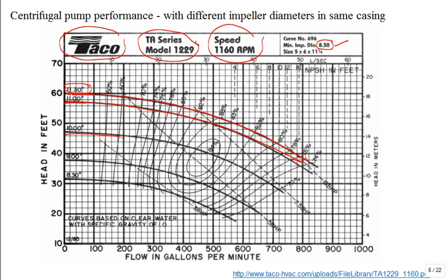This is the 10-inch diameter impeller. This is the 9-inch impeller. And the 8.3-inch impeller. Don't go lower than that. So they have these impellers. That would be the maximum and down. Notice I forgot a slow introduction. What's on the x-axis? Flow rate in GPM. Okay. What's on the y-axis? Head in feet.